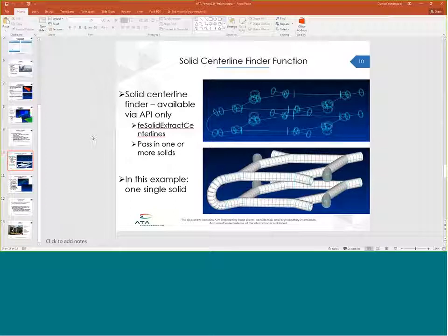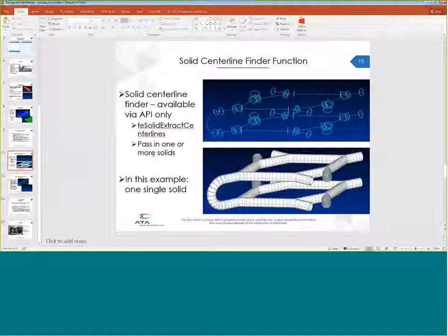Moreover, it actually also creates property IDs. And the properties are fully defined with their areas, moments of inertia, and everything you would need to have a fully functional PBEAM. So in this picture you showed here, there was a tube of a complicated structure. This is after you already used the function, and now there are center lines going all the way through. And then you can easily mesh and have a nice mesh for beam elements, very easily done.